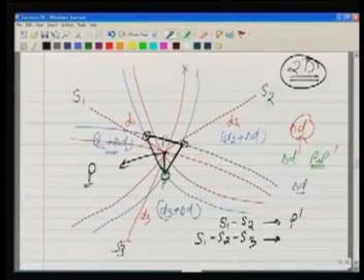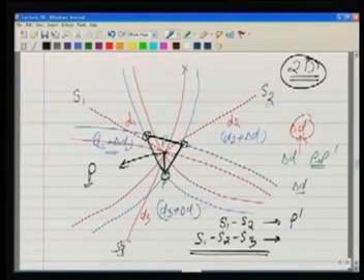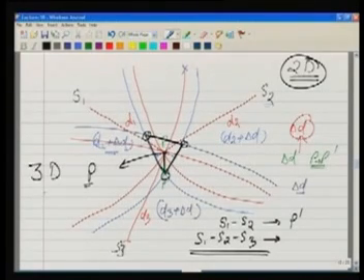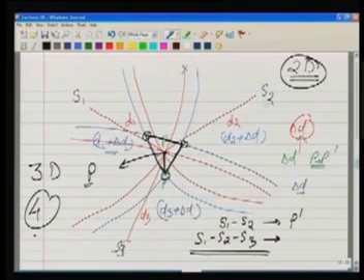The example which we just discussed is in 2D, but in the case of GPS, it's a 3-dimensional problem, so we will have to add one more satellite. The meaning is, in the case of GPS, even if there is error in the receiver, its effect can be eliminated by observing distances to 4 satellites. Because in the 2D example, we saw that 3 satellites can solve the problem. So in the 3D problem, we will have to have 4 satellites.